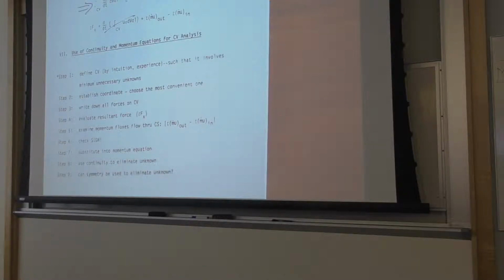And that's where now the m dot, should you care about the sign? Does it have direction? Come to confuse you. What about the velocity u? Same thing, you have to deal with that. And that's why I want to separate them into step 4 and 5. Then you check the sign again in step 6. Make sure you are consistent with the sign with the coordinates.